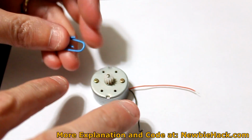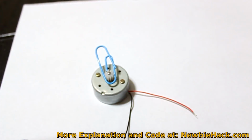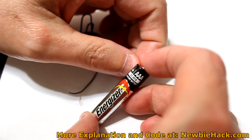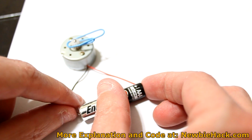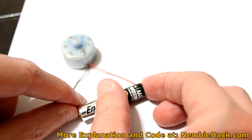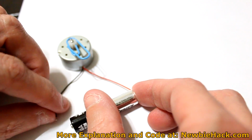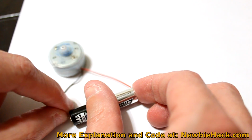I'm going to put a paper clip on it so I can see the spinning of the motor and the direction. So I'm taking the positive and putting it to the red lead, and the negative to the black. You can see that it's turning in a clockwise direction. Now if we turn the battery around and have the negative pole on the red and the positive pole on the black, it turns in the counterclockwise direction.